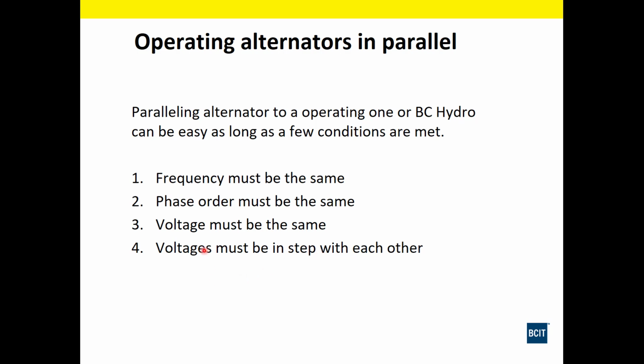Okay. Number one point here we need is our frequency must be the same. Number two we have to look at is our phase order must be the same. Our voltage must be the same, and our voltage must be in step with each other. Okay, we're going to have a look at these right now.